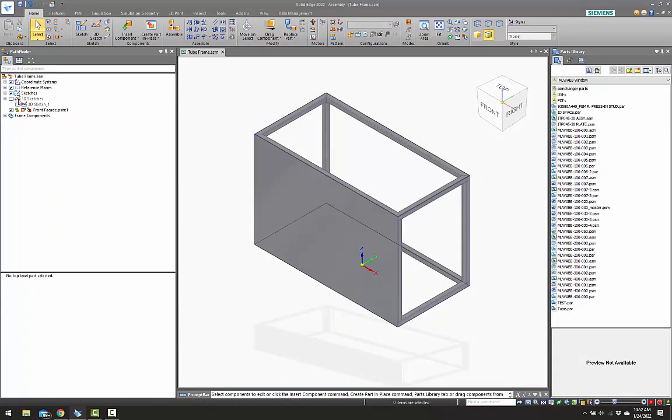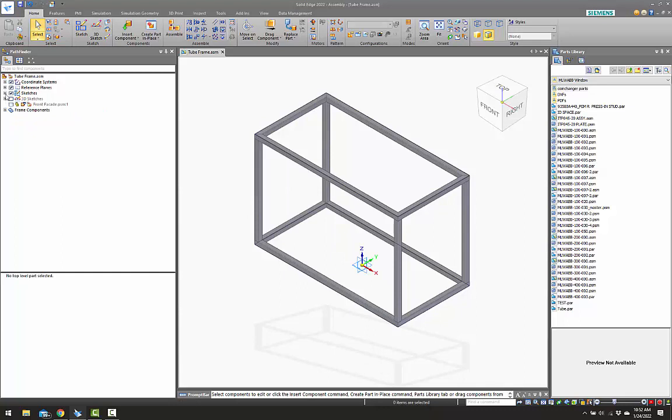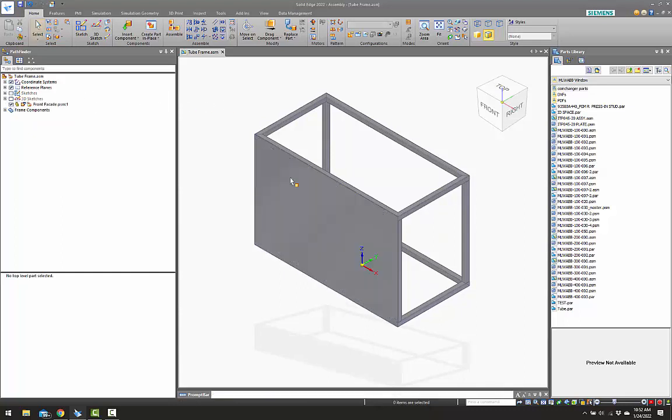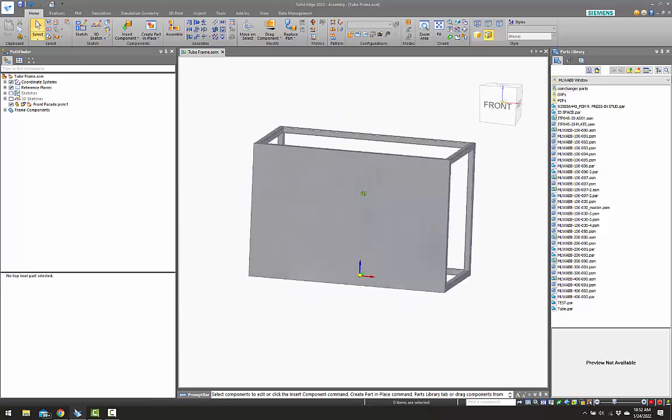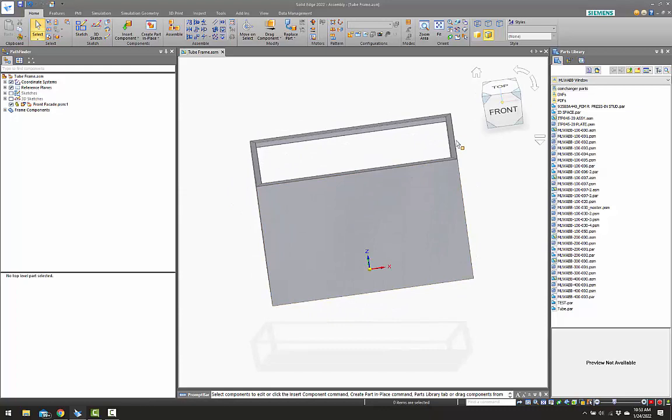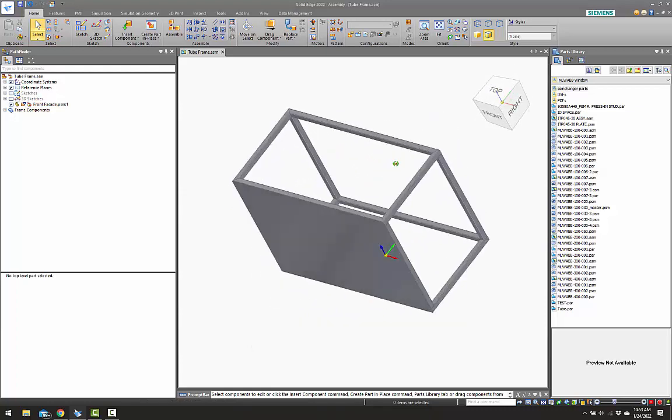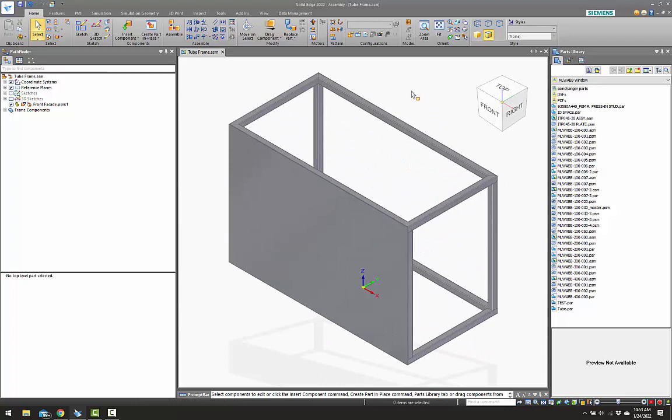Let me turn some sketches off here. Let's turn that one off. Oop, went too far. Turn that part back on. Now you see that I've created a facade, front facade, that is the exact length and height of my frame. So again, I could have done the same thing by saying I want a 72-inch by 48-inch piece of sheet metal, 14 gauge, placing and mating it.